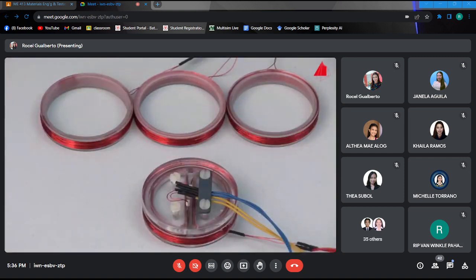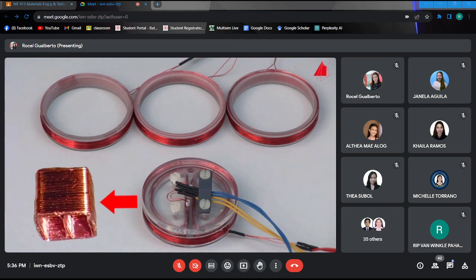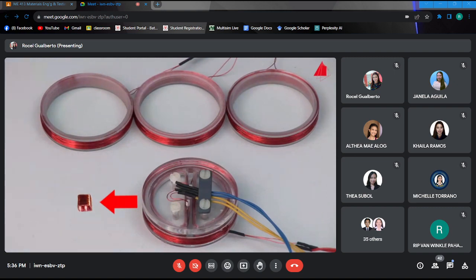To demonstrate the basic principle, we have chosen rather large coils so far. However, the disadvantage of large coils is that only large defects, such as our rough saw cuts, can be detected. In practice, mostly very small coils are used, as shown in the example on the left-hand side. In this way, also small defects can be detected. The coils don't have to be round or D-shaped, but can also have a rectangular cross-section.